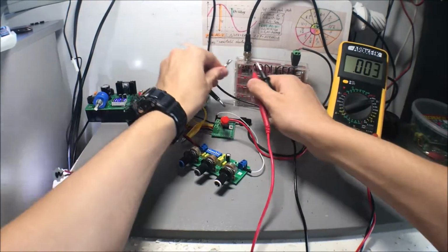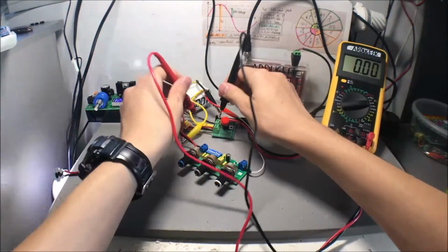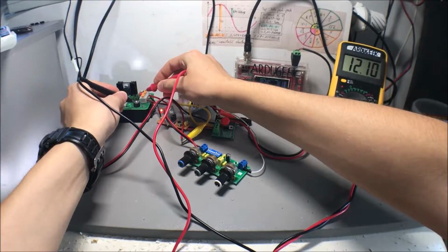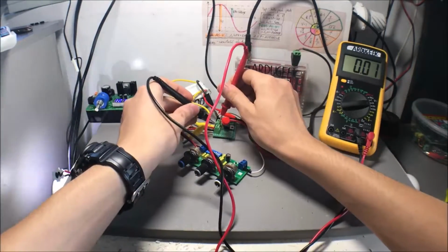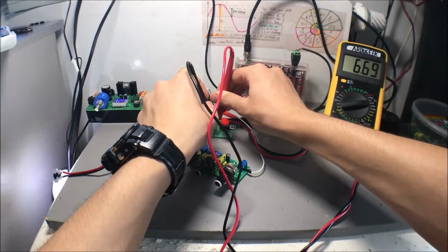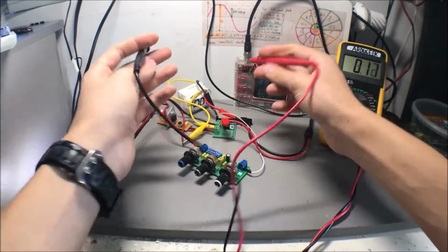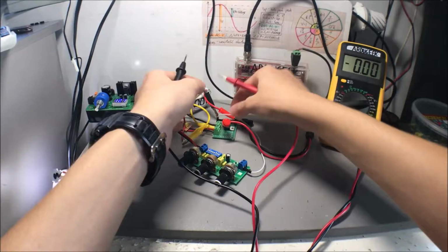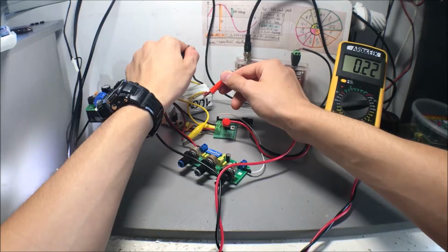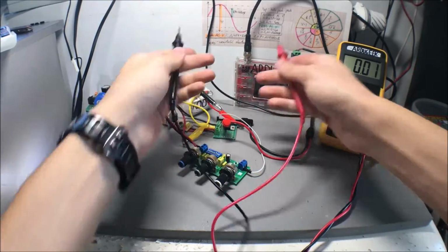Of course I can measure another thing for you, mainly this constant current source. As you can see, this is our input voltage, which is 12 volts, and now I am measuring the voltage after the converter, and as you can see, it's 6.7. The current is mainly the same, but my meter will not show it because it is not DC current, because we are blinking this LED very fast, so it doesn't show it pretty accurately.